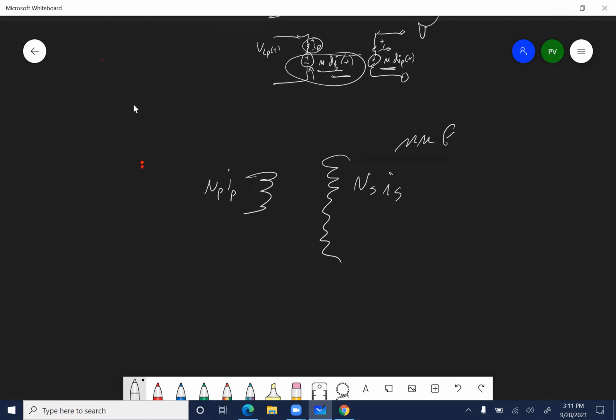That's why people here have their smart chargers. Anybody here have a charger that they just put on a desk and then you just put your phone on it? Why does it work? Why isn't your skin burning when you pick it up? It's coil to coil. Yeah. So there's no electrical energy being lost. I mean, there's a little bit in the air because that magnetic flux travels away. So it's not as efficient as a hardwired one, but there really hardly is any power loss.